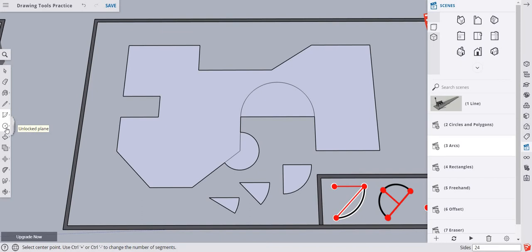Okay, we're going to go from there to the 2-point arc. 2-point arc starts on the edges. So we go 1, 2, doing a diameter, and then we kind of draw in to create a bulge. Now, you can create like a big bulge like this or a small one, but it actually will snap to exactly a half circle, which is kind of nice. So I can create one there, end point on the edge, end point on the edge, and again, if we get on the right surface, and then it says half circle, and we know it's exactly half a circle.